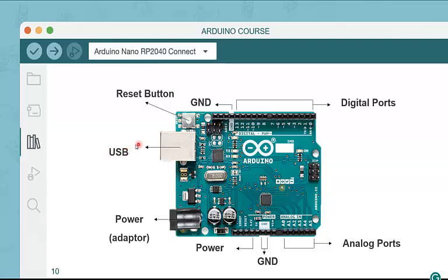We have here the USB port. We have the power adapter here. We could supply voltage to Arduino using VIN here, which is located beside ground. We have here 2 pins ground beside this ground, and we could take power from Arduino, as we said last slide, from this 5 volt output pin or 3.3 volt. Also we have here analog pins from 0 to 5.